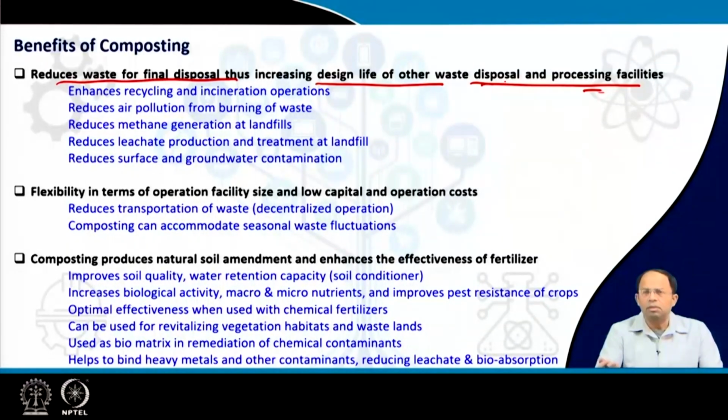That means if I do composting, then automatically the contamination of the dry waste or the recyclable waste reduces, and we can use those recycling facilities in a more efficient way. And also in the case of landfills or even some other facilities, the design life, or the period for which those facilities are designed, could be extended. Now, what are the other benefits which come along with this?